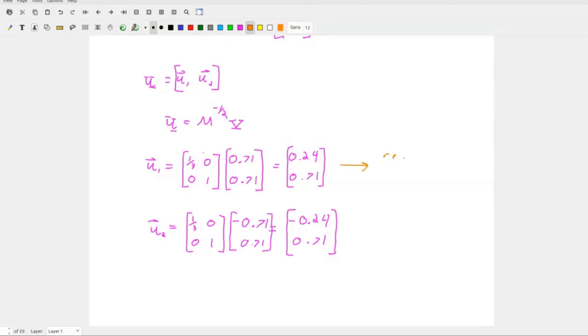So we renormalize back to 1. Again, mode shapes are just shapes, and so when you plot them, we want one value of the mode shape to be renormalized back to 1, and then we do that again here. But you have to normalize as you go through also, so you get the correct value.